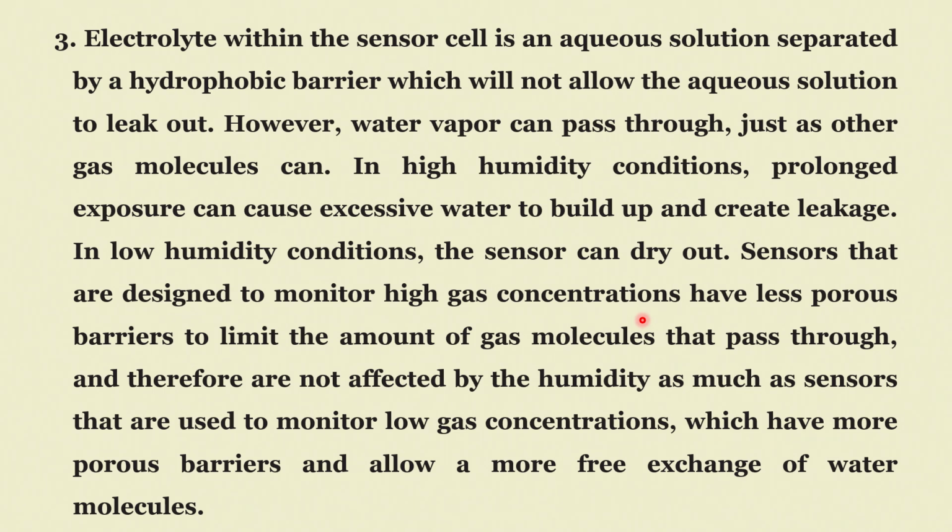And in low humidity conditions, the sensor can dry out, that is also possible. Normally, sensors designed to monitor high gas concentrations have a less porous barrier. Why? High gas concentrations do not require very high gas passage.